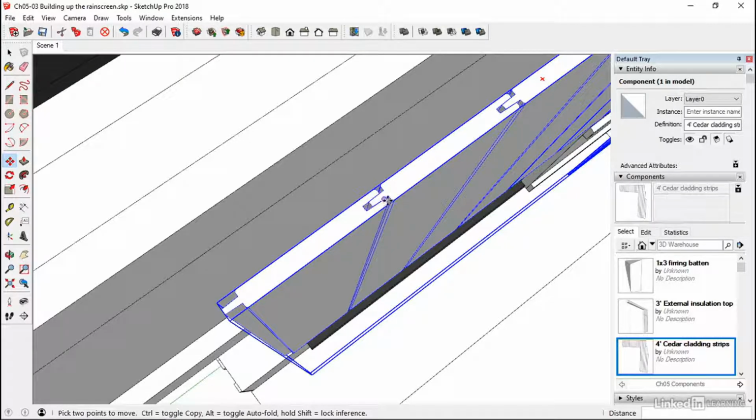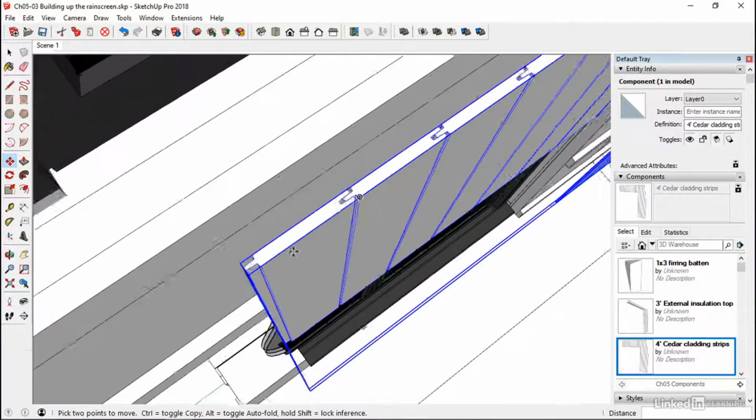So you want to drive that in closer to that. Then this is not going to touch that, in case it swells or expands. And the reason I've left gaps instead is simply because when you render this, the gap gives you a nice little sort of finish that you don't necessarily see without a gap in there.